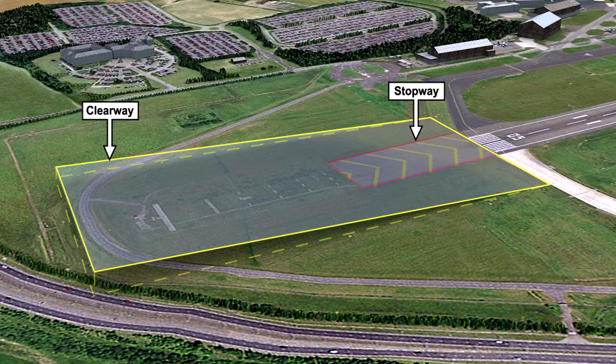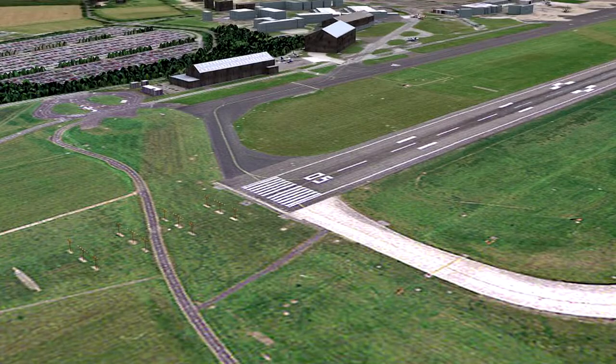Having discussed the extra runway extensions of stopways and clearways, we will now focus on three more specific distances, other than the TORA, which you will need to understand. The first of these distances is the accelerate stop distance available, or ASDA. This used to be known as the emergency distance available.